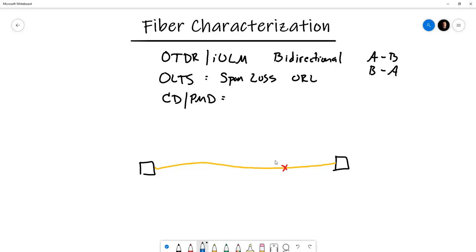And so, for instance, if we had to do what we called a section throw at that time, basically create 2 splices within the same location because we didn't have enough slack to join those 2 pieces together at the break, right? And so when we did that, we would essentially have 2 splices very close to each other, usually within 100 feet or so, right? So, we'd have a section throw about 100 feet. And so now you have 2 splicers, right? So you have 2 splicers typically, and you want 2 splicers because you need to get this thing done quick, right? After all, it is a break. So you have 2 splicers, 1 in each pit.